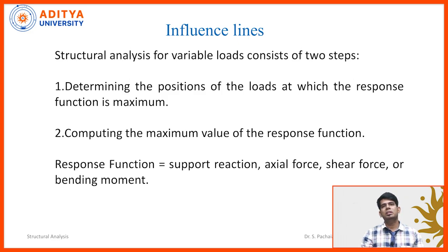And then computing the maximum value of the response function. For example, this is the deck slab or the beam, and on the top of that, the vehicle is moving. First, I am going to keep the load somewhat nearer to the support, and then at the center, and then somewhat away from the right support, and then exactly at the right support.